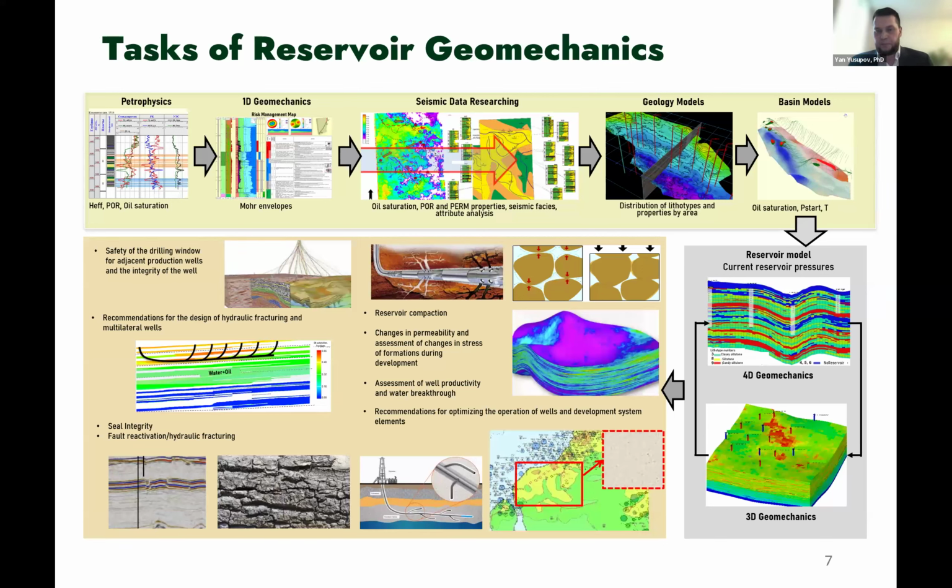It depends on customers' needs. And we need to understand that 3D geomechanics is only a static model, with information about stresses and mechanics at only one time step. If we want to know the stress distribution over time, for example, from the beginning of field development to the end of the field, we need to make a 4D geomechanical model where the fourth dimension is time. It can be a discrete model with equal time steps or not equal time steps. It depends on our needs.